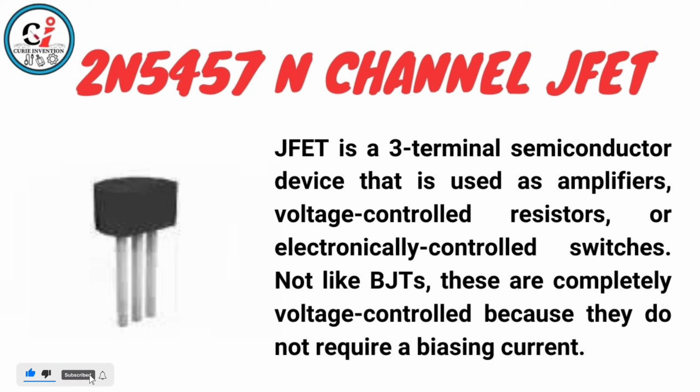2N5457 N-channel JFET. A JFET is a three-terminal semiconductor device that is used as amplifiers, voltage-controlled resistors, or electronically controlled switches. Unlike BJTs, these are completely voltage-controlled because they do not require a biasing current.